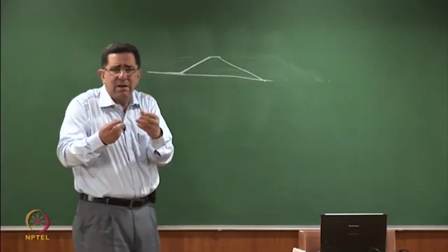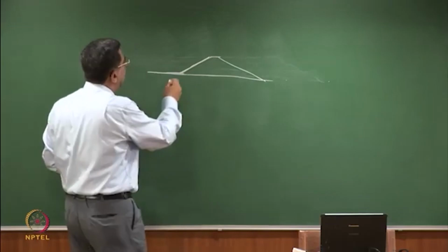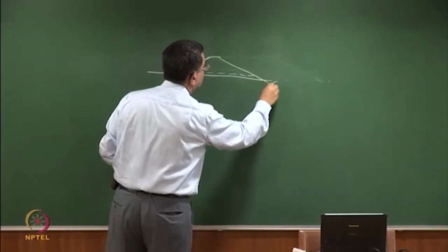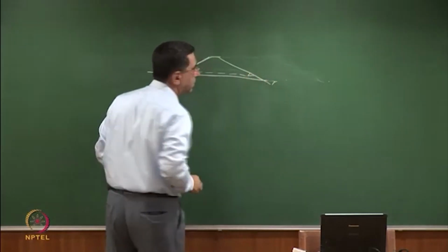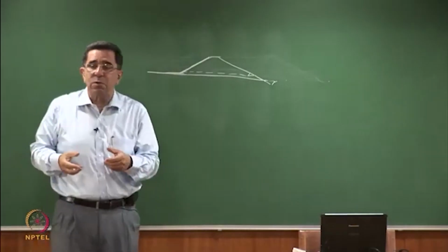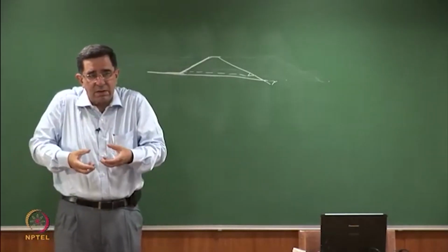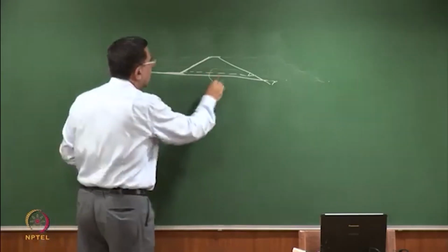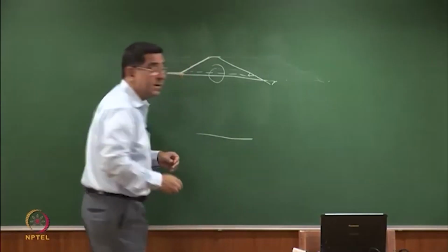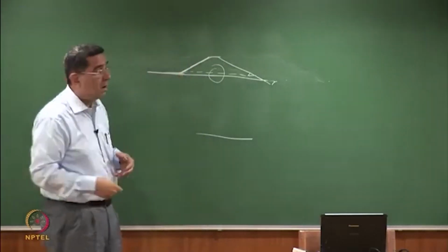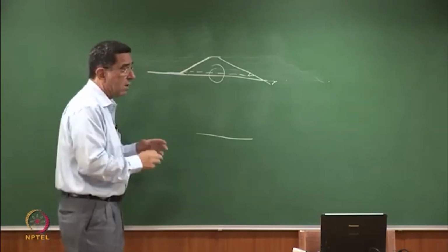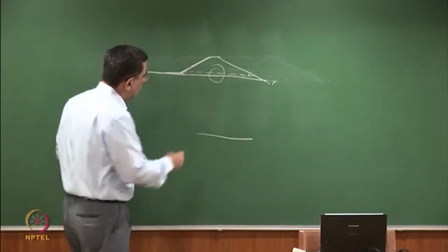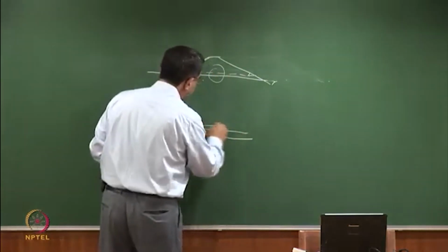A simple example is, let me put a pipe. If I put a pipe, then I can have a toe drain here and the water can be collected, and I can have a rock toe here. But the problem with pipes is, with time, if there is differential settlement, then the pipe can crack. So one of the ways of doing this is, make a drain, a trapezoidal drain, or you can make a trench drain, whatever you want. But the idea is that from here you should be able to carry out clear water. What does a trapezoidal drain look like?